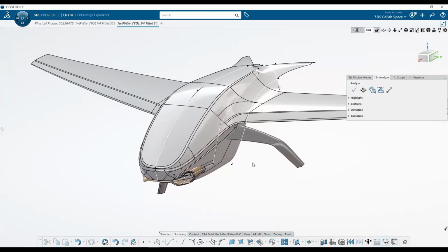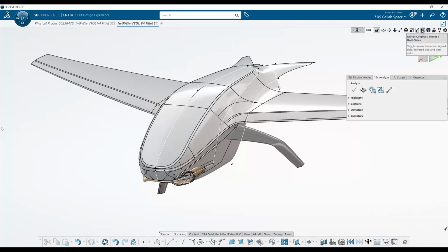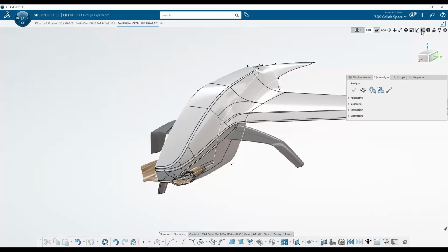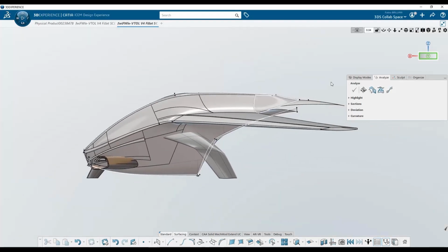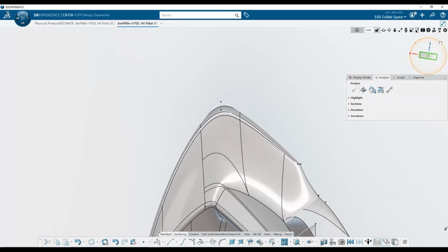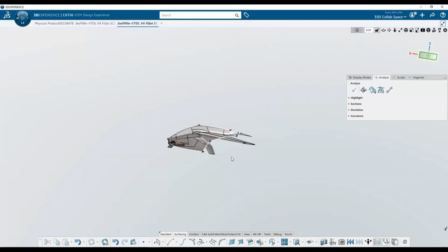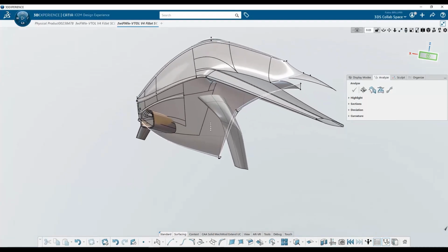Let's keep going and have an overview about the V-bar. You will find very useful commands that enable the user to set the plane to the current view, set a view to the current plane, define parallel mode view or perspective mode view, and the visual symmetry: left side, right side, both. We also have the non-proportional scale, what we call stretch view, enabling you to modify the scale of the point of view unproportionally and get more precision during sculpting.